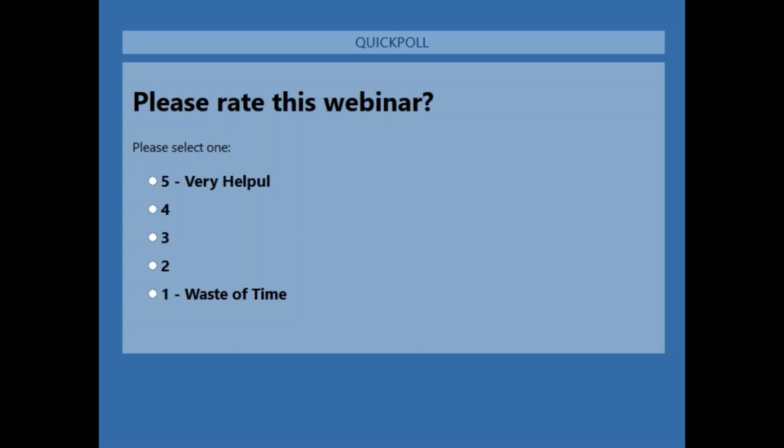Oh, here's one that just came in. So Chun says, also on the same question, can the VAV box or fan power box have high pressure at the inlet and low pressure at the outlet in terms of construction code, operation, maintenance, and make sense at all? Yeah, you can select your VAV box for higher pressures. It's going to start depending on what you're calling high pressure. To me, high pressure is more than 3 inches of static. And you could have a VAV system that has a 3-inch static inlet. You got to select your box for that, obviously.